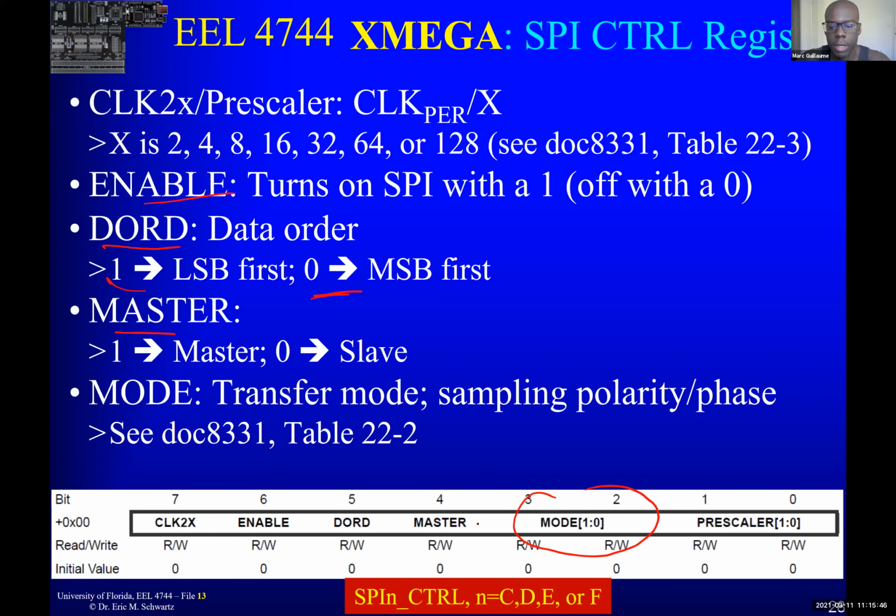Great. So just to clarify, even if you put a 1 in bit 4 and the slave select line goes low, it will still override it? If it's set as an input, it'll override it. Basically, it won't work. It's a master that is told to be a slave, and so any code that you wrote for it isn't going to work right. It's not going to operate.